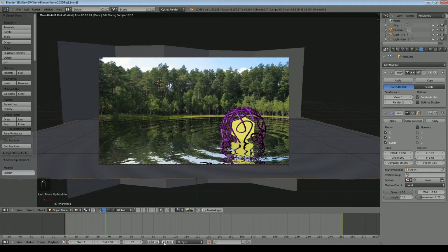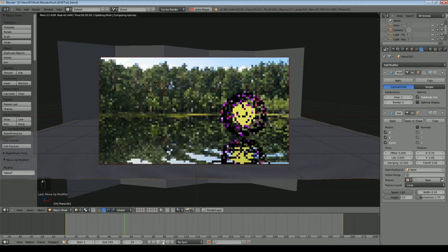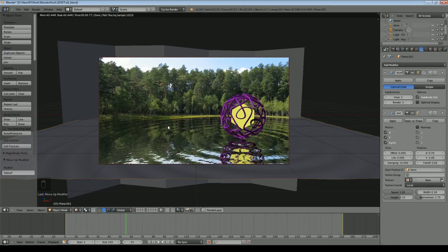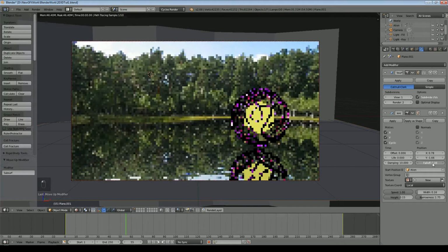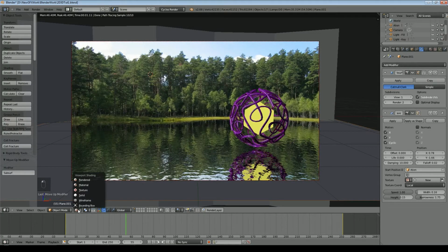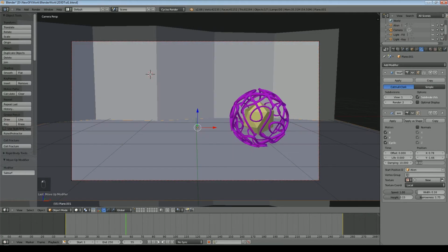By the time the object is there, you can see we're getting ripples running across the entire pool. And what you may not want is, in fact, those ripples going all the way across, because this is meters, or would be in the real world. So what you might want to do is use the fall off. So we start to turn that up, and we'll just come out of this view, go back to 0 for a moment, and let's just turn that. Now you can see we've got some ripples here, but nothing out here.